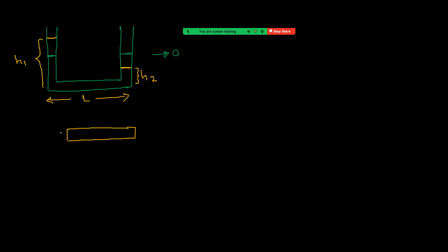Now I am focusing on the left side force. It is equal to pressure P1. If this area is A, then P1 into A is the force by this part of the liquid on this liquid column at this face. In the same way, because of this liquid column, the force acting on this face will be P2 into A.